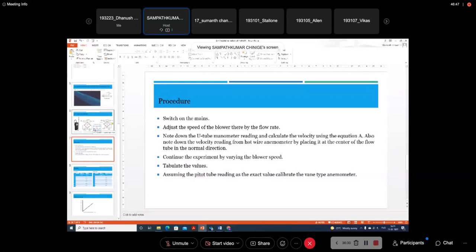You should understand that in experimentation, when you touch anything, first the question is to find the uncertainty of the measurement by the instrument. You have to find that out. If you are not finding the uncertainty, or if you are not calibrating the instrument and you are using it, your repeatability will be wrong. You will not get the same values when you do it for the second or third time, and people will always question your results. So with the aim that you should understand that, I actually gave this.